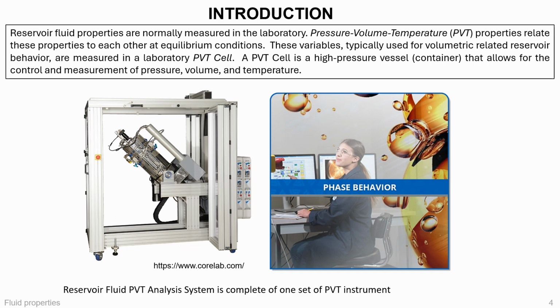In reservoir engineering, PVT properties are essential because they control volumetric calculations and pressure-volume behavior during depletion and injection. The key idea is reservoir fluids behave differently at reservoir conditions than at surface conditions, so we need a systematic way to relate those conditions, and that's exactly what PVT analysis provides.